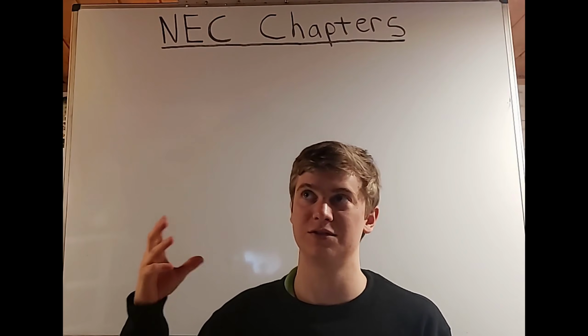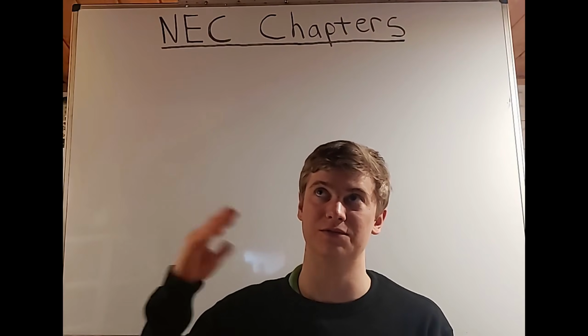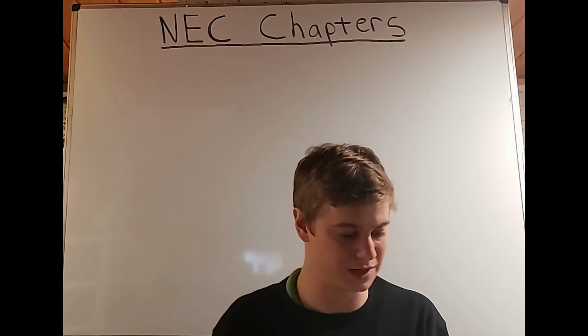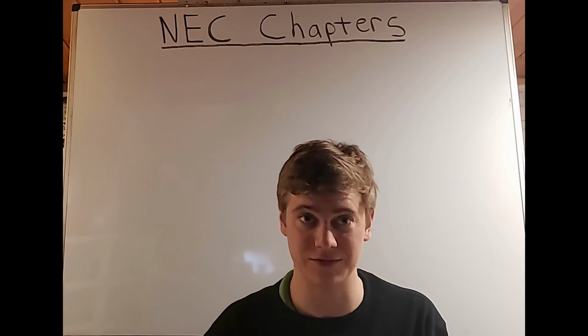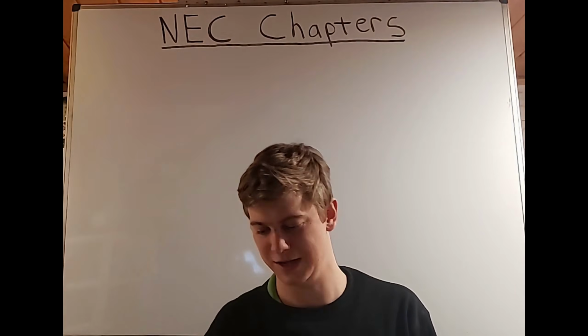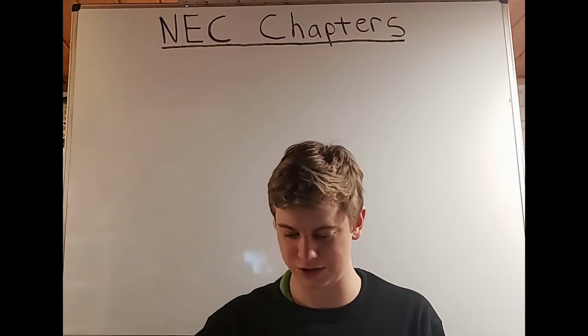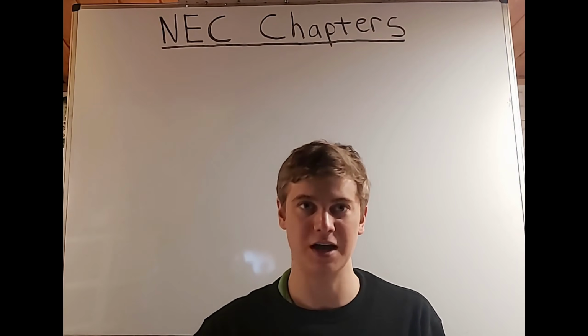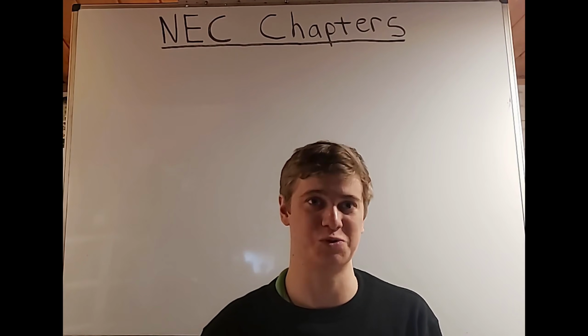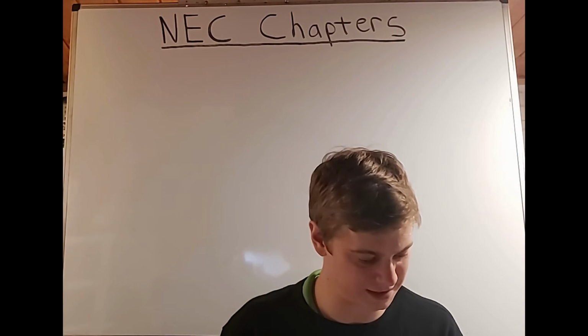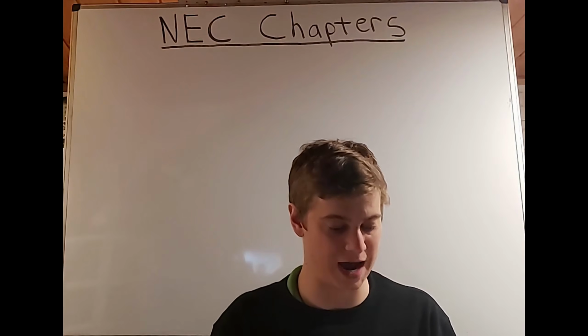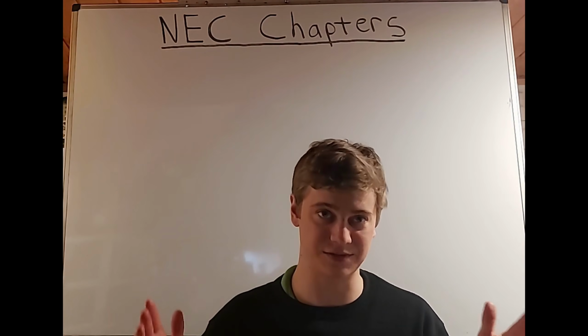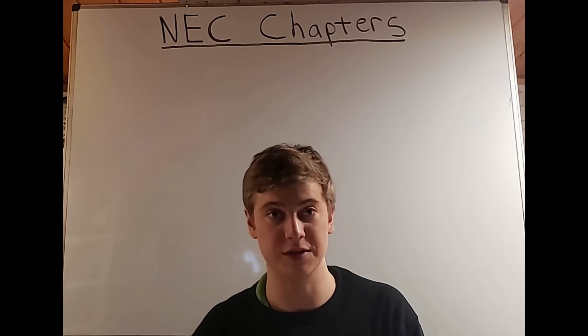Okay, so when you have certain things operating at over 1,000 volts and you want to find the definition, now you know that's going to be Part 2 of the definitions. If you don't know that and you're just flipping through the definition section, you might not realize that you're going through 3 different sections of definitions. So it's really good to understand that. Part 3 contains definitions that are applicable to hazardous, in other words, classified locations. And you'll be using those enough.